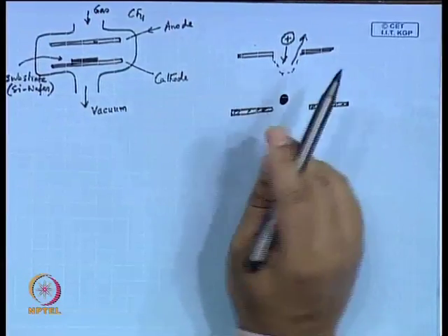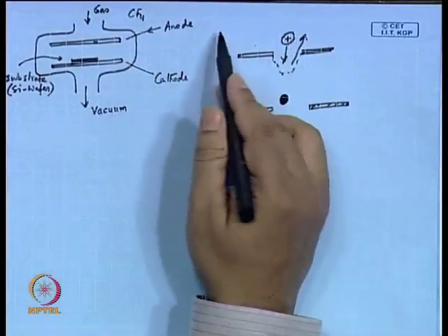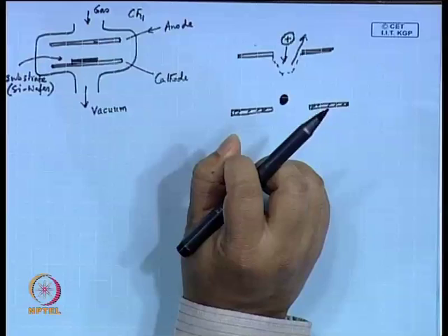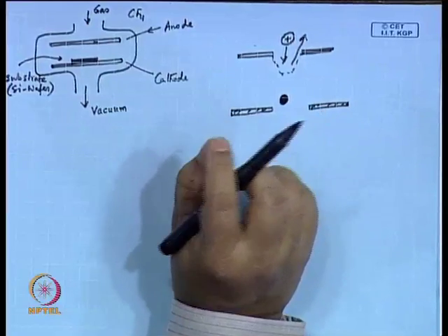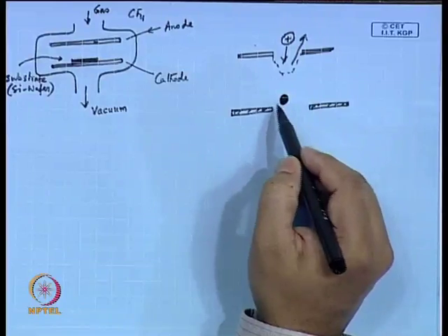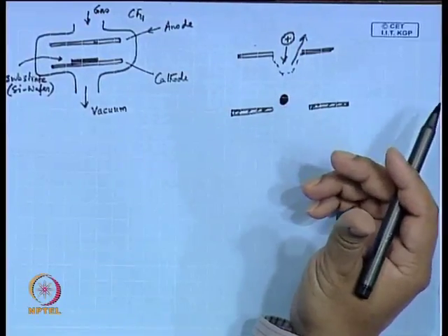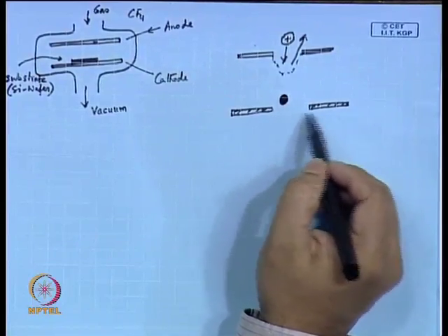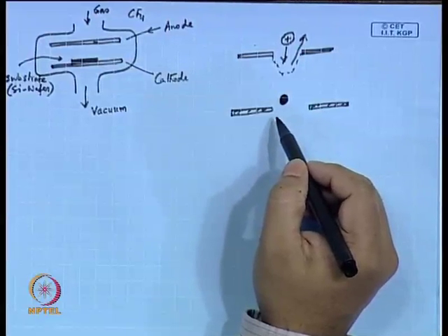Sublimated means XeF2, a solid XeF2 was somewhere nearby, and that XeF2 has been sublimated. That means it has gone from the solid phase to the gas phase, and one gas molecule XeF2 is floating around. It has a high diffusivity, you know, gas molecules can diffuse easily. So it is getting in contact with the exposed surface, that is what we have.